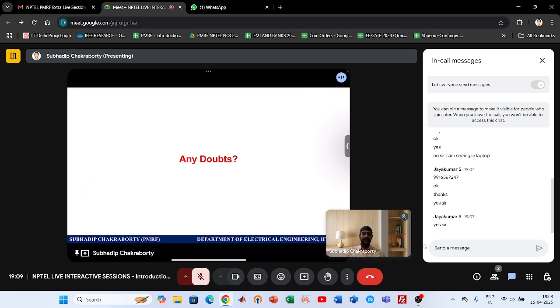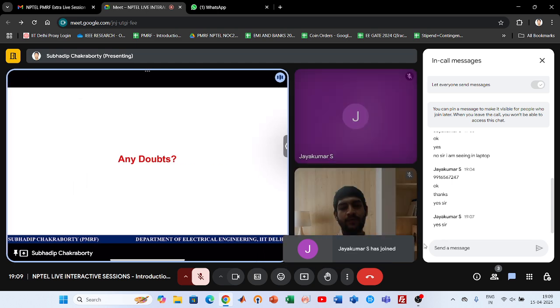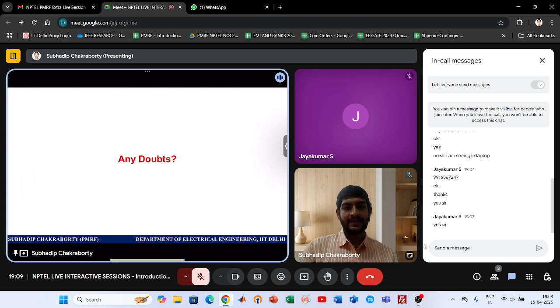Basically we'll learn the concepts through the discussion because the concepts are easy, and we'll first deal with the basic instruments, the PMMC type instrument and the moving iron type instrument for measurement of voltage or current, as you know. Those two are very popular instruments, and we use them in the laboratory for measurement of voltage and current, right? But the working principle of both of them are different, and both of these types of instruments actually show different parameters of the signals that you are measuring.